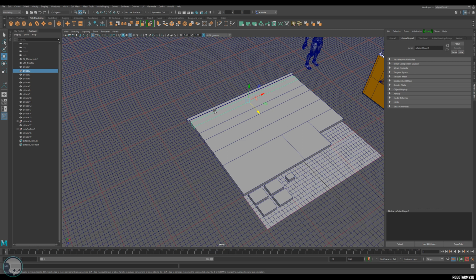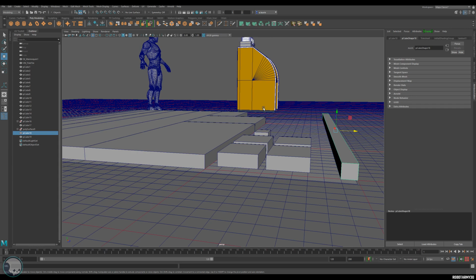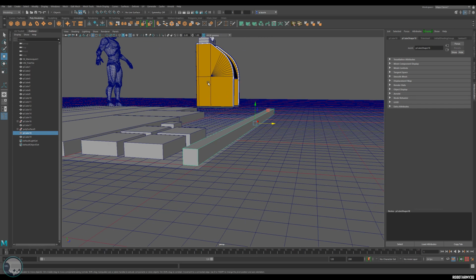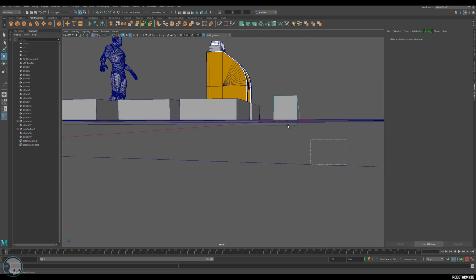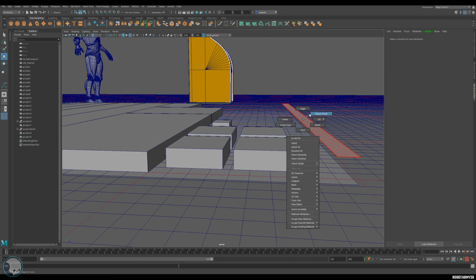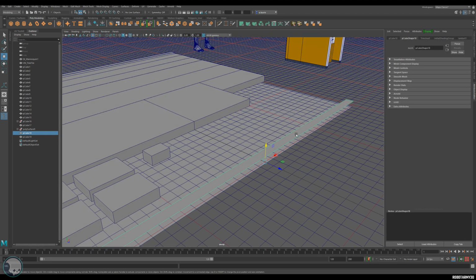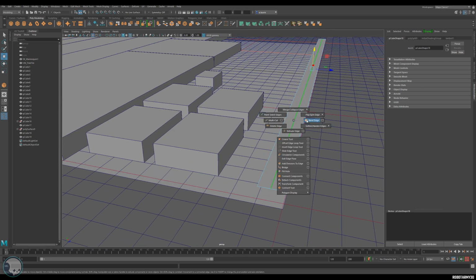So I think I'm also going to grab the second piece here and move that down to the bottom. And this is actually going to be a bevel, like a panel bevel, so that I can make an alpha map with it and lay that over the surface as a floating decal map to create the illusion that there is extra bevels in the surface. So I'll make that now. What I'm going to do is select all the bottom faces and delete them. So we just have this, and you can move it down, don't have to have it really high. Then I'm going to grab these two edges and do a cut. Okay, and then I'm going to bevel that cut too.